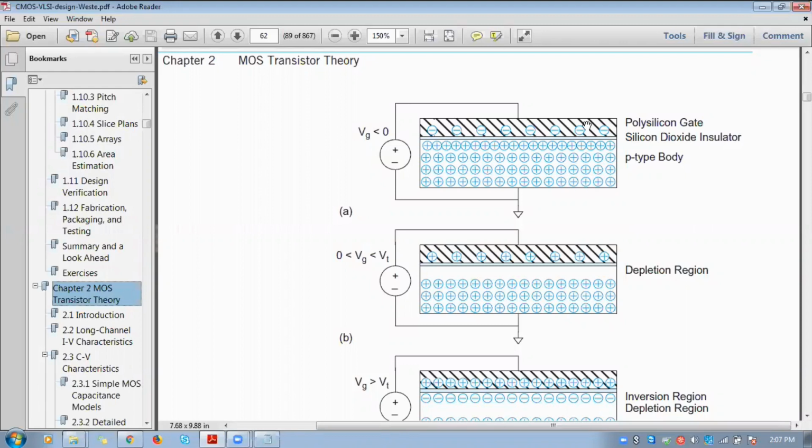So why is electron-hole pair recombination not happening here? In between we have the insulator. The silicon dioxide layer won't allow electrons or holes to pass through. As we are applying a negative charge, the positive charge carriers will accumulate near the silicon dioxide layer. They can't pass through, so they accumulate near the silicon dioxide layer. This region is known as the accumulation region.